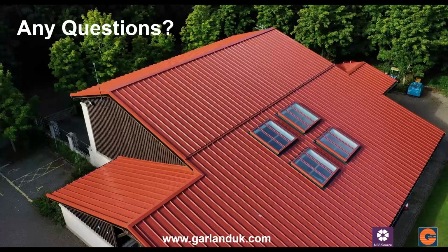Hi there, Lee. Thank you for your question. Ultimately, it's the longevity of the system. We replace a lot of single ply roofs, and our concern with single ply roofs is the robustness and, as I mentioned, longevity of that system. Whereas something like a bituminous membrane can last 30, 35, 40 years. Although single ply is a relatively new technology in comparison to something like bitumen that's been around for tens and tens of years, it's purely the robustness and the longevity that we're looking for. So that's the reason we don't do single ply. We never have, and in honesty, we never will. But we're happy to keep replacing them.